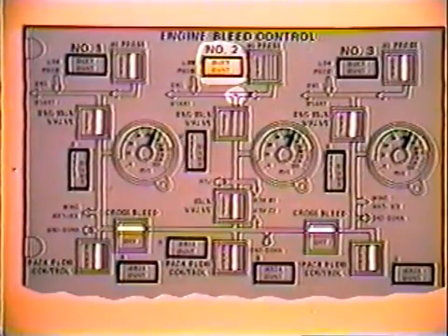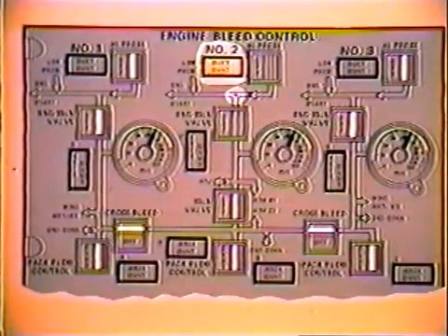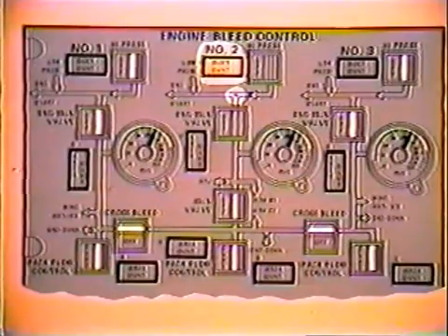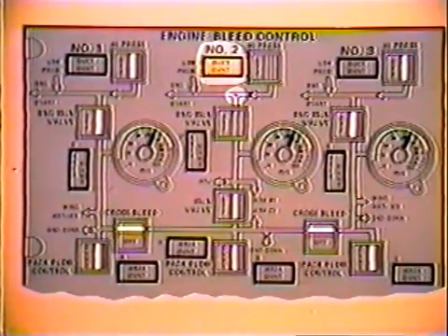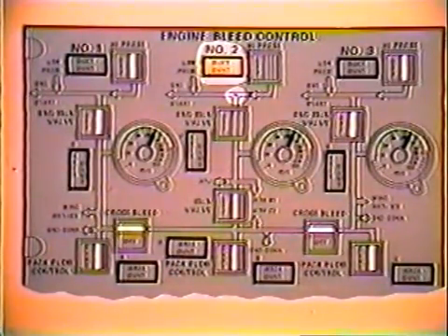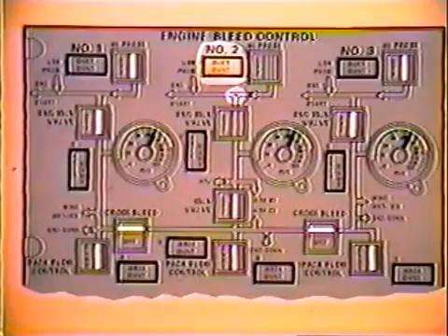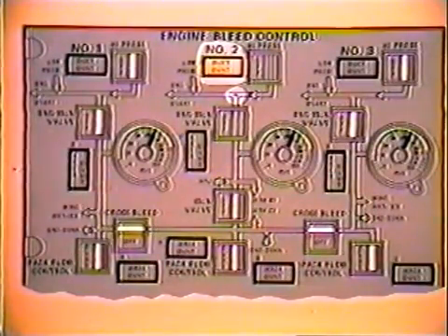The duct overheat system is designed to provide protection in the event of excessive bleed air temperature inside the duct, just above the engine isolation valve. The protective action will be the closing of the high pressure and engine isolation valves. These valves will be locked closed until the duct overheat light extinguishes and the valve switch lights are unlatched and relatched.